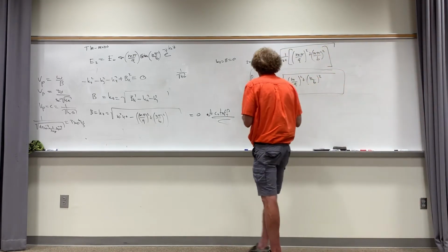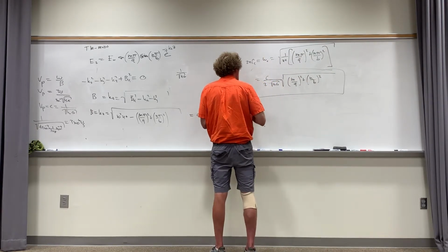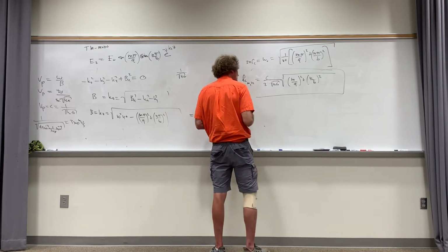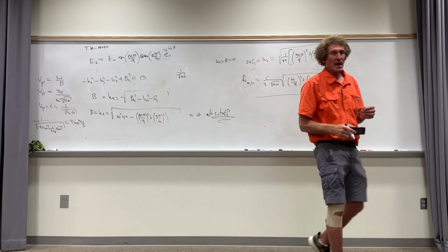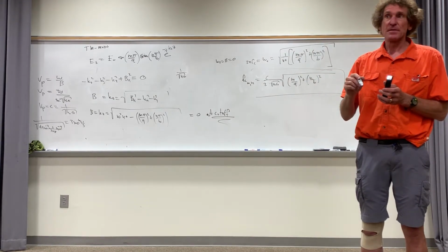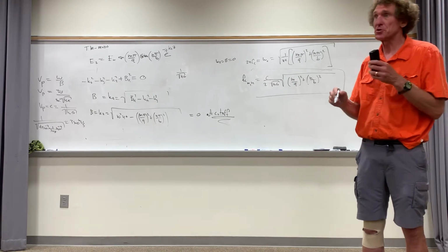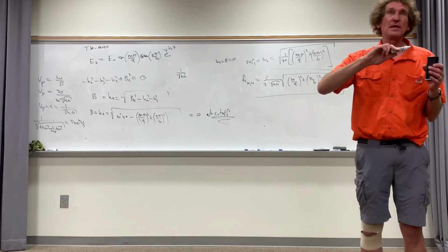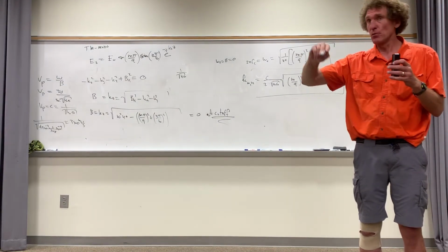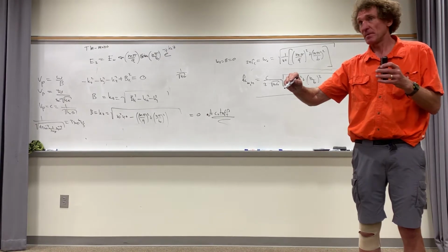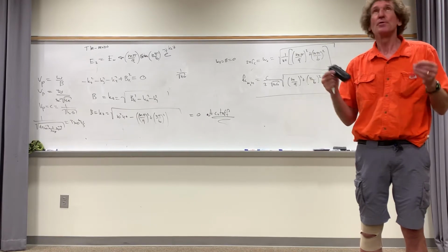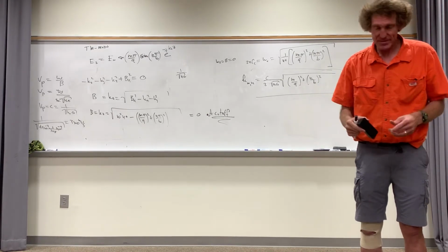Now, generally, that n and m have to do with the mode numbers. So what I do is put down f cutoff and then m comma n. And that means, remember how m and n had to do with the sine wave variation? If it was a 2,0 mode, it means in the x direction it wouldn't have half a sine wave, it would have a full sine wave, basically two half wavelengths, a full wavelength.